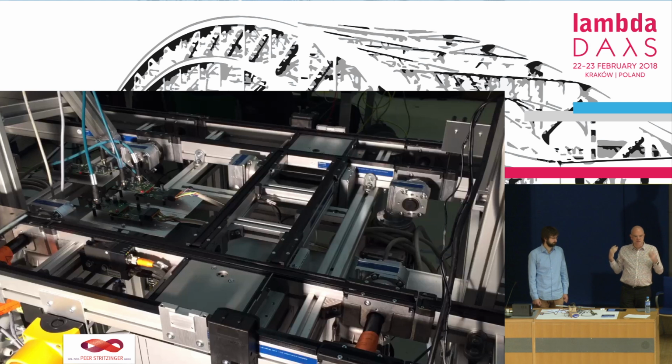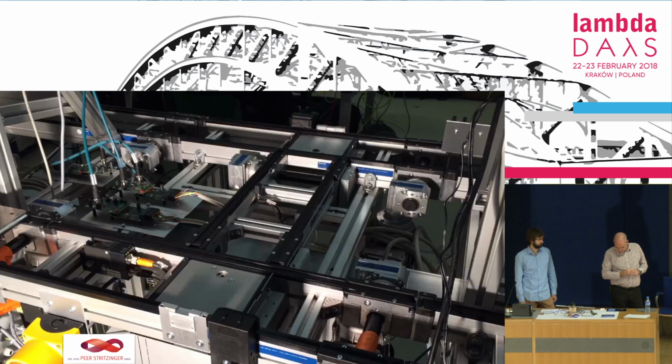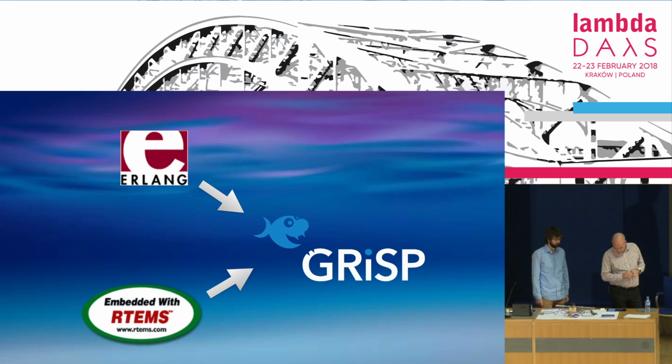This was just a standard Erlang system running on a hard real-time operating system, which makes it already more hard real-time than if it runs on Linux, on the Raspberry Pi, because Linux basically preempts your Erlang system, and then you're not getting anywhere. The kind of hard real-time that we get here is event-based.